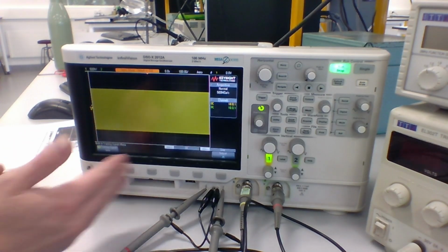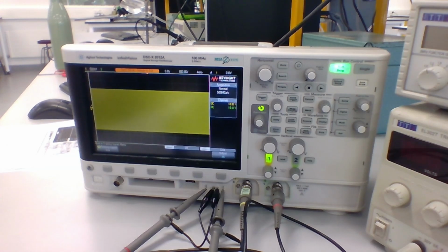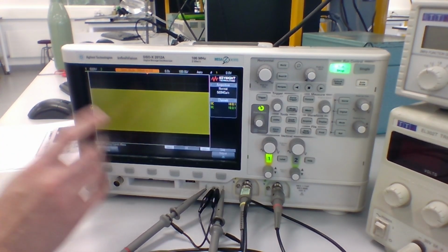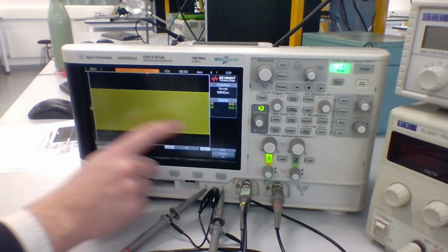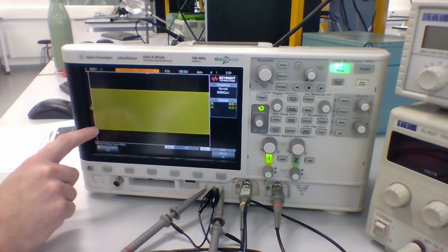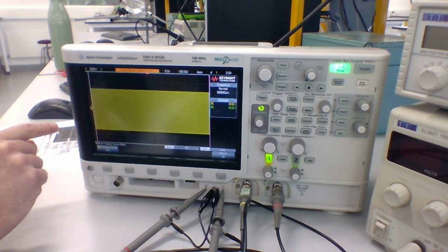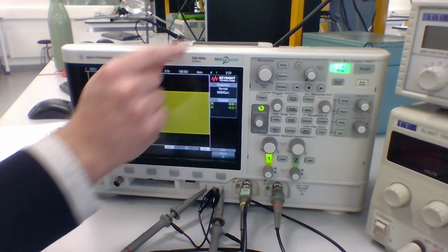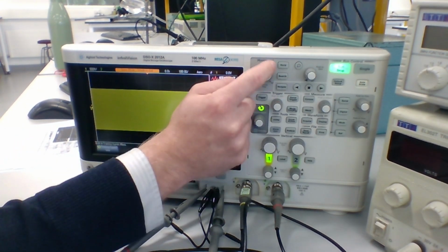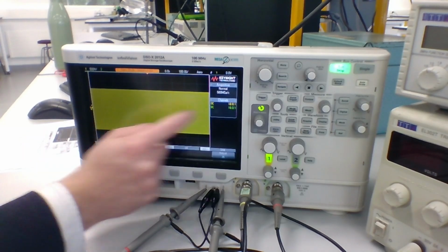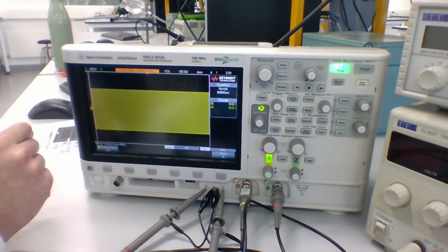Okay, so we fixed the vertical scale, but right now the horizontal scale is not very good either. Everything's kind of compressed in this one big blur. So we can change the horizontal time scale as well. On the vertical axis, we have our voltage at the moment. On the horizontal scale, we have time. We can change that by using this horizontal dial up here. The large horizontal dial changes what we call the time base or the time scale.